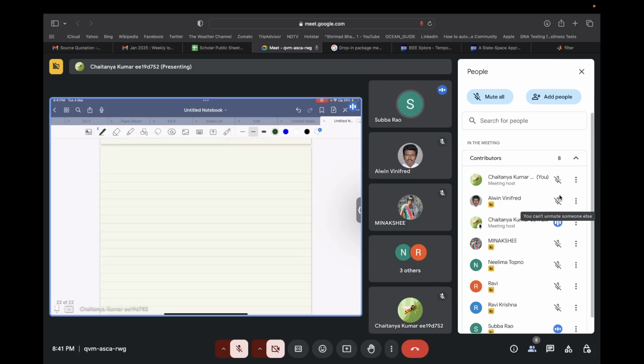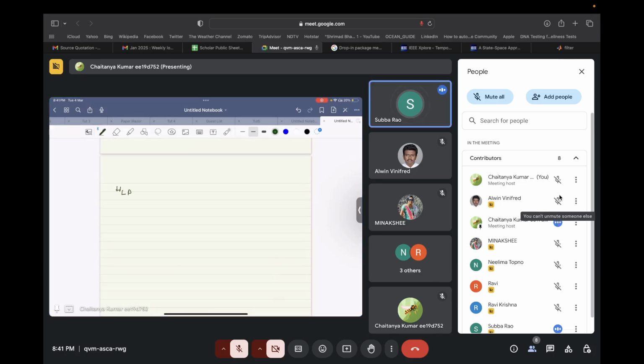So we had this low pass case as 1 plus S by omega naught, and having S equal to j omega, omega equal to 0, S becomes 0 and HLP becomes 1. Omega equal to infinity, S becomes infinity, and HLP becomes 0. Right?